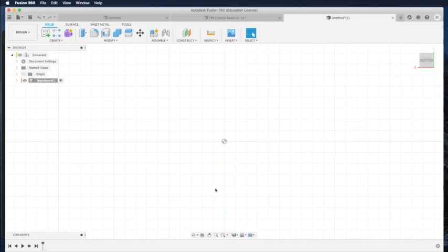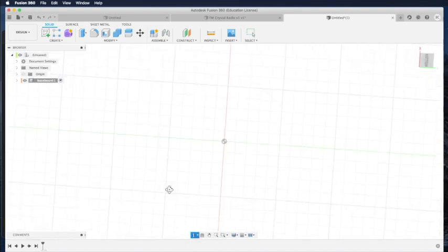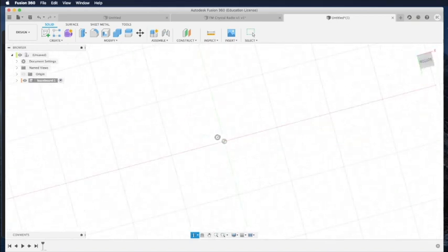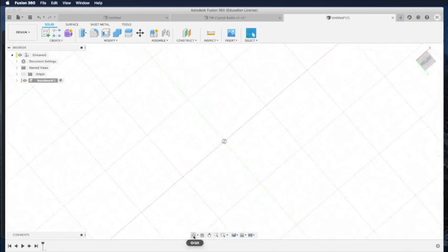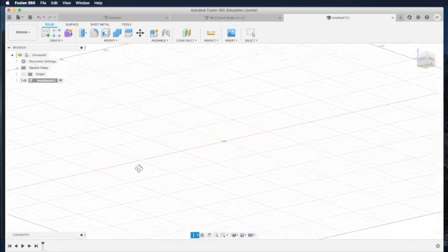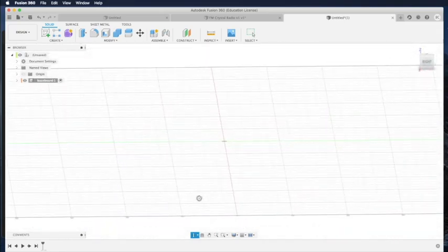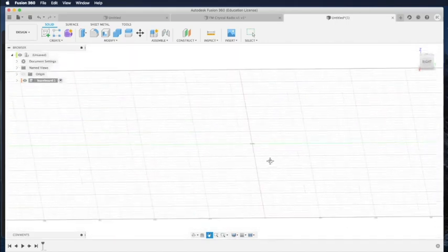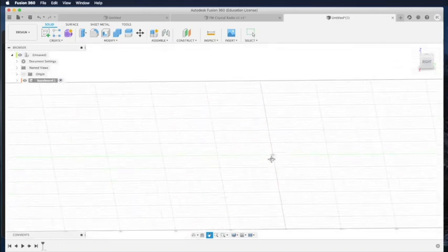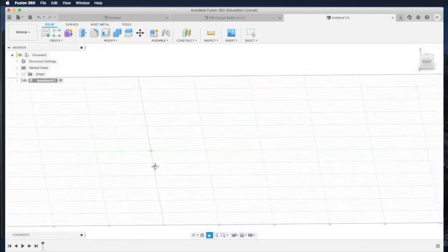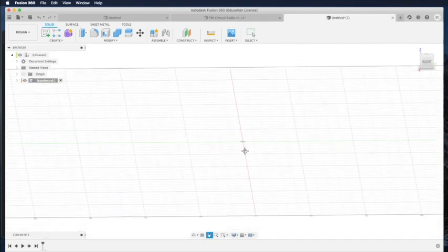The other way to move the screen is to click on this multi-dimensional viewer. You can click on it and then click the left button to drag it in different ways, so it will turn your orientation like that. Once you are done with it, click on the escape key to get rid of it. The other way is pan, to move horizontally or vertically. So click on this hand icon to move the whole thing up, down, left, right. But it won't allow you to twist and turn. It will just allow you to move up or down, left or right. Okay. Once you're finished, click Escape.